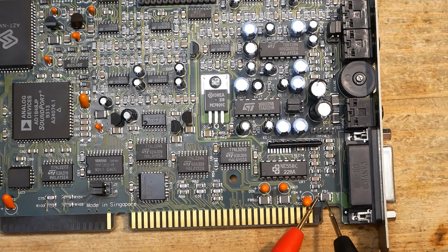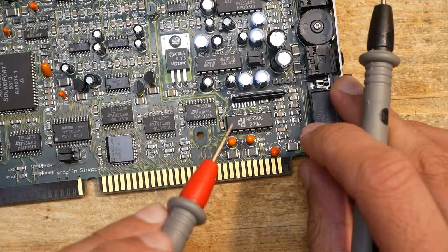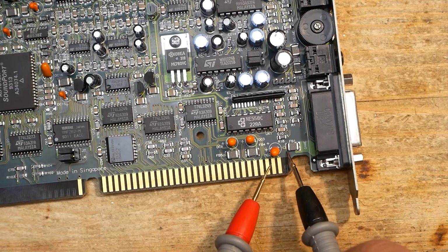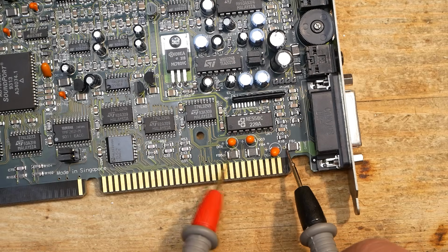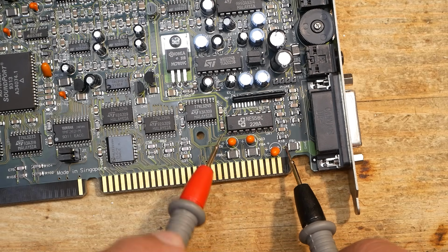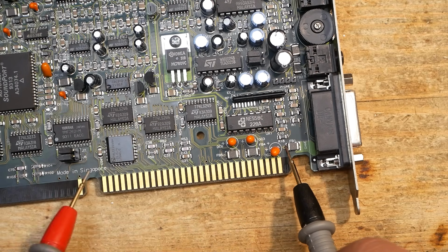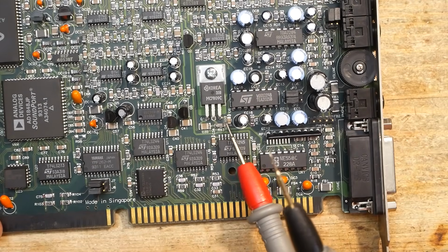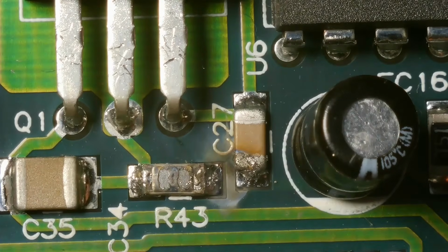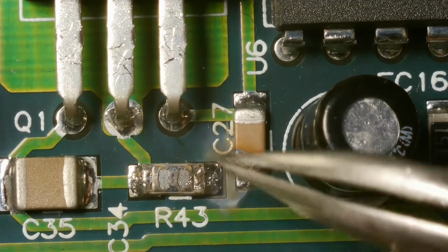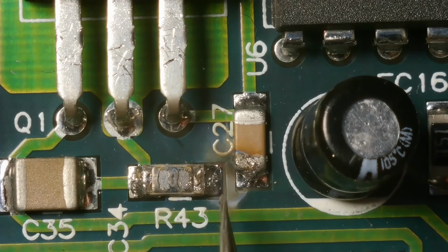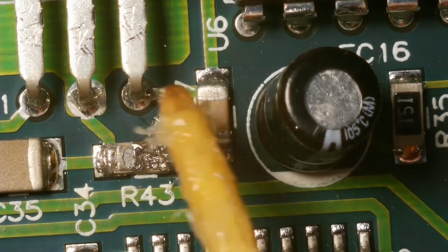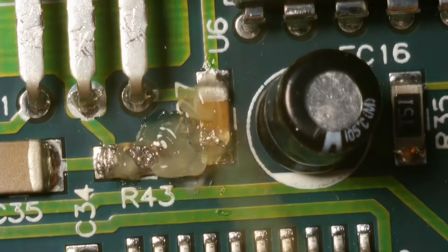Oh, this ferrite bead seems to be dead. I'm not quite sure, but it looks like this is going towards the game port. Maybe something was connected to the game port which shorted the 5 volts to the ground and killed the coil. Well, currently I have no explanation for what happened here. It looks like there was a big spark. Maybe a screw fell down on the PCB and shorted the parts. Hard to tell. Now, where we have an overview of all of the cards, let's start with this one first.